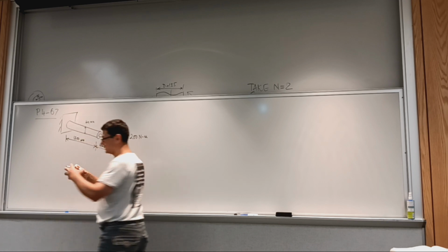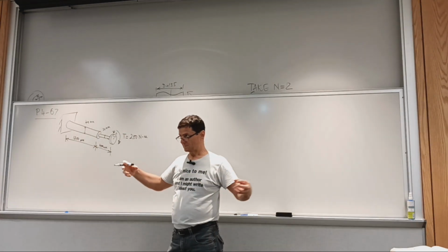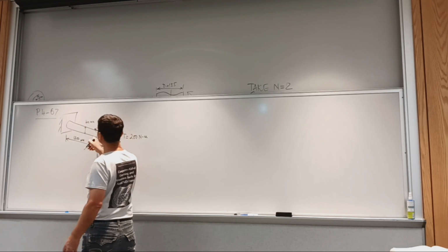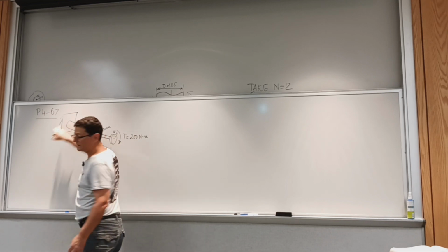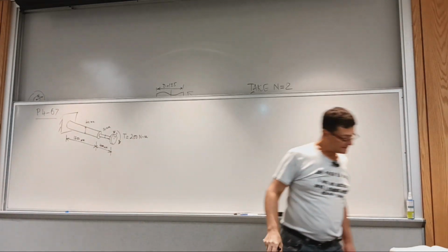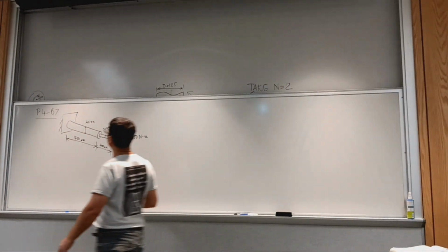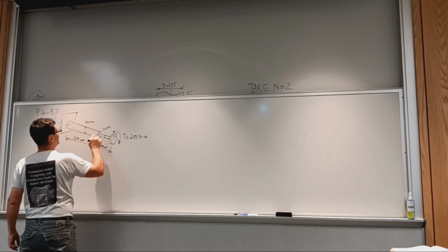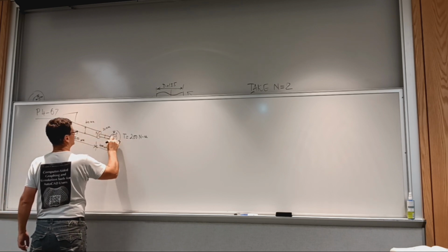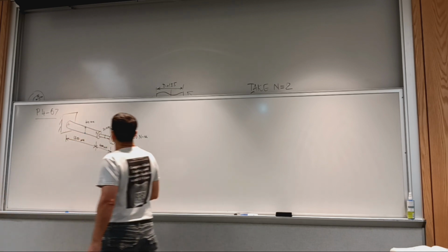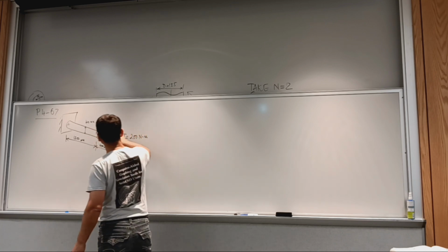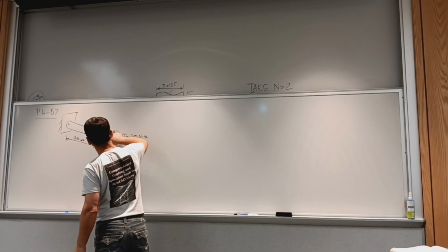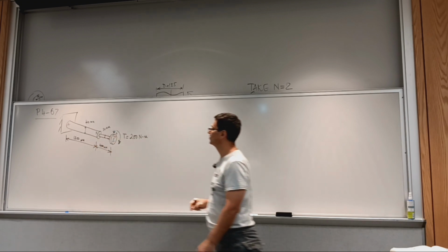It's what it is, and we want to calculate this one. But the shaft is not continuous in diameter, it has two sections. So we need to distinguish between the relative rotation between the fixed end and where the step is. There's no labeling, so you can call this A, you can call this B, right here, and C here. Or maybe C on the invisible face of this disc that you use as a pulley to apply the torque.